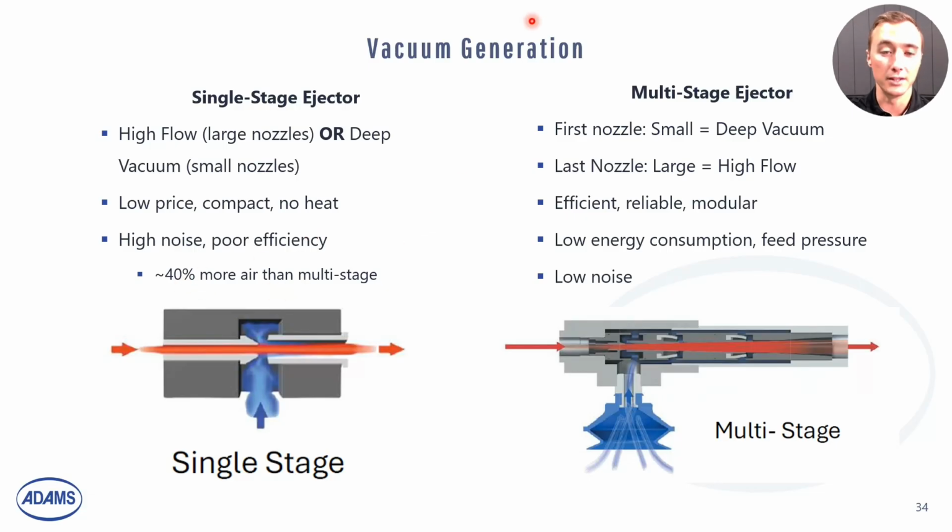So these ejectors, they actually use compressed air to create vacuum. So the compressed air is going to come into the system here on the left, enter the ejector, and it actually goes through a venturi to speed it up, which creates a void or a space that's in a vacuum condition. And then at the other side is the exhaust from that compressed air, speeding through the system.